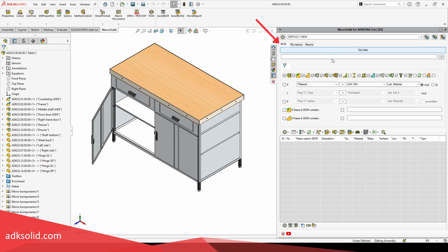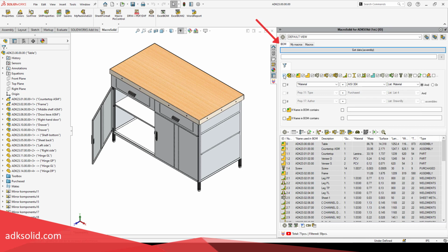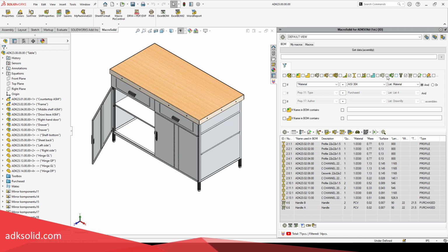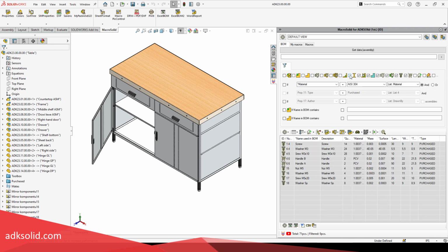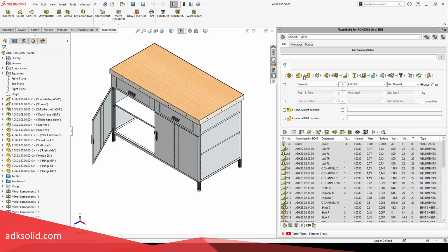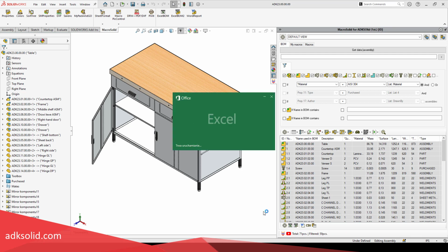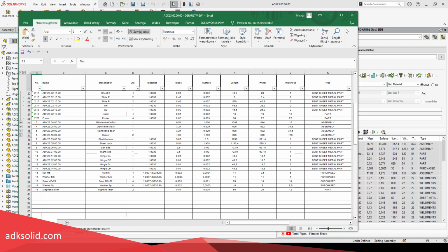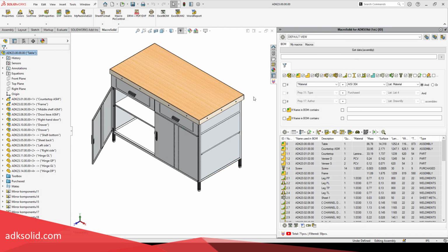This time, I will focus on the Bill of Materials tab, and I will discuss in detail the possibilities of downloading data from the model and filtering components. So, as I already mentioned, after getting the data from the model, you can filter the components by type, file properties, name, and then sort them. All this, so that any macros work only where they should, and that you could have data specified for reports, statements, material lists. I collect data from the model, taking into account the user's preferences.